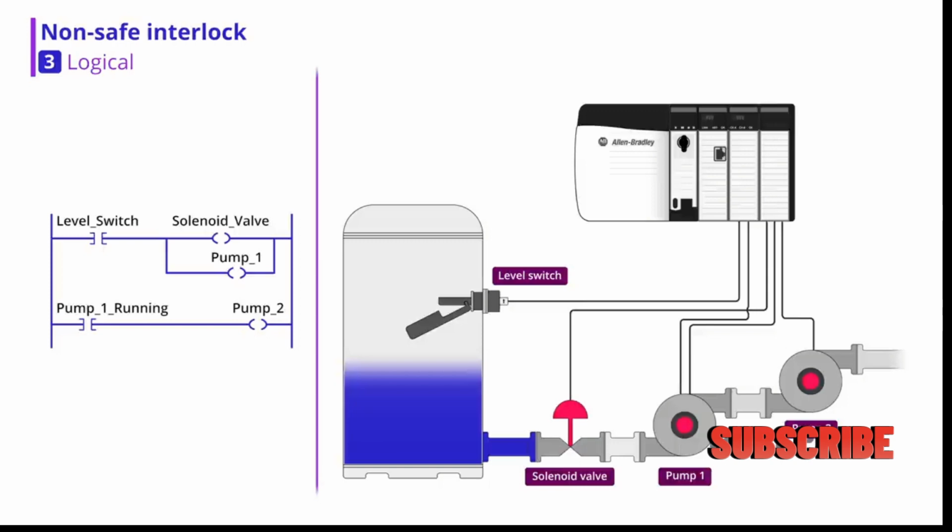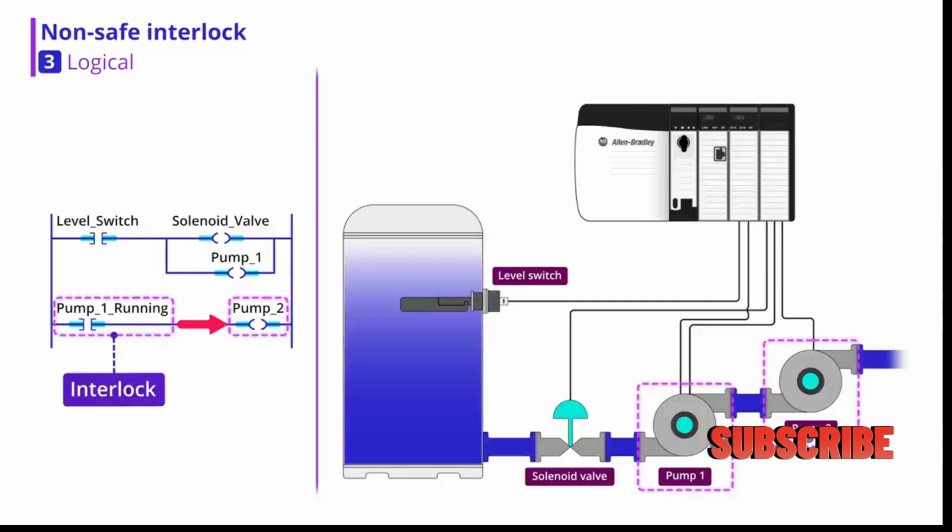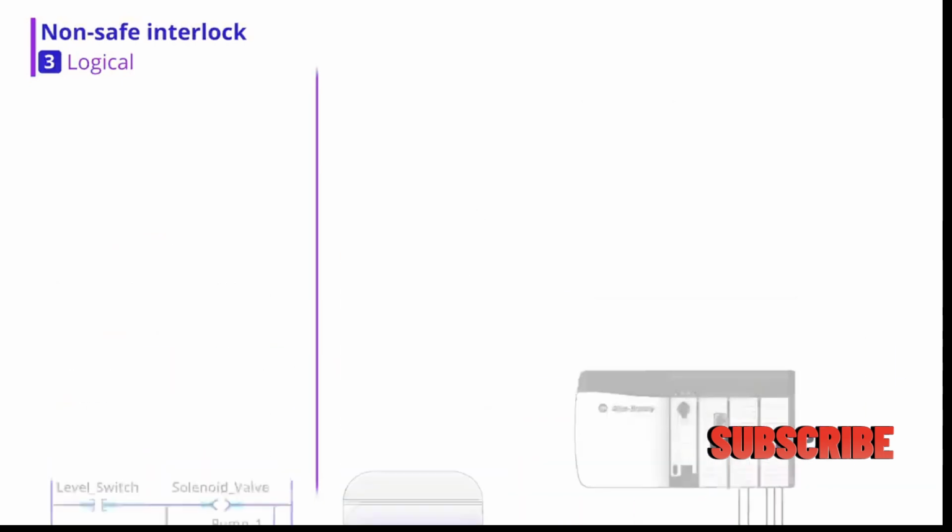An example of this is a pump downstream of a process that needs to be running to start the next pump in line. To do this, you would take the pump's running signal and put it in series with the output used for the next pump. This will ensure that the second pump will not start unless the first pump is running. So here, the first pump works as an interlock.